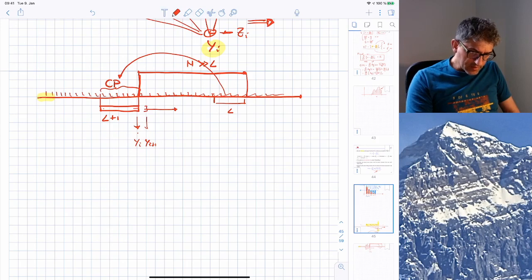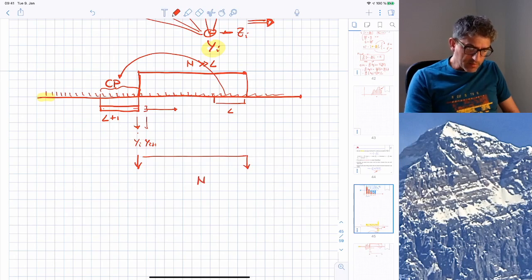Then you can see that the symbols taken from this point to this point, so we have n output symbols, can be seen as the so-called cyclic convolution of the impulse response with the block of n symbols.